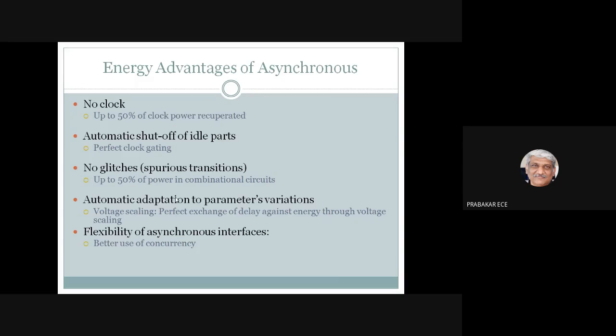Now, the energy advantages of asynchronous circuits. What are the advantages of asynchronous circuits? No clock, so 50% of the clock power can be recuperated. Because even though there is no data, since the clock is running, every block will be working. But here, since there is no clock, the unwanted blocks can be simply removed, so that the clock power consumption will be reduced. There is also automatic shut off of idle parts.